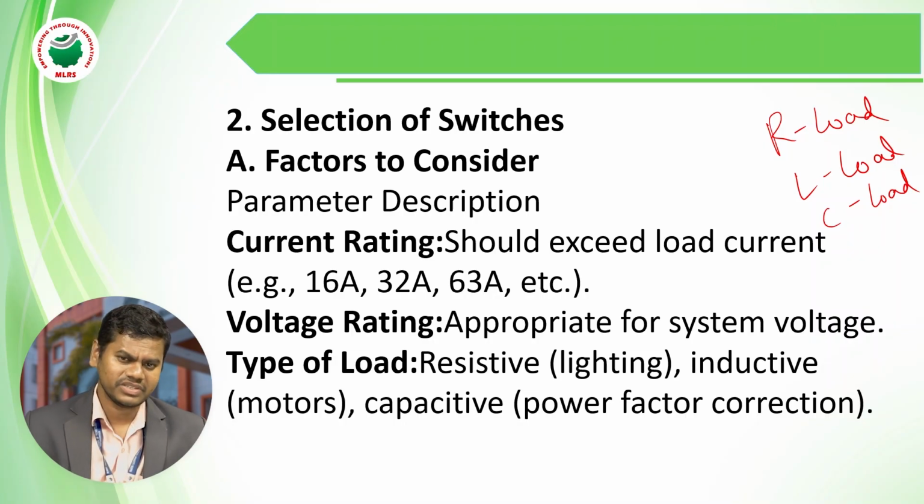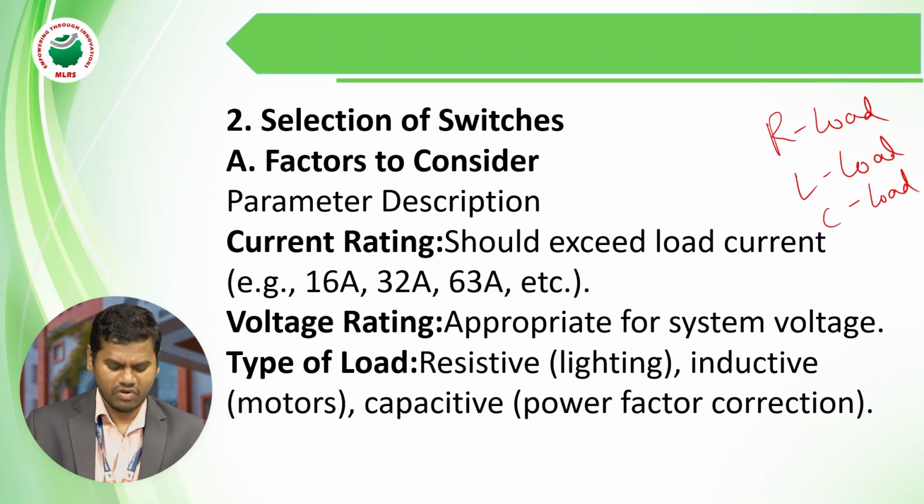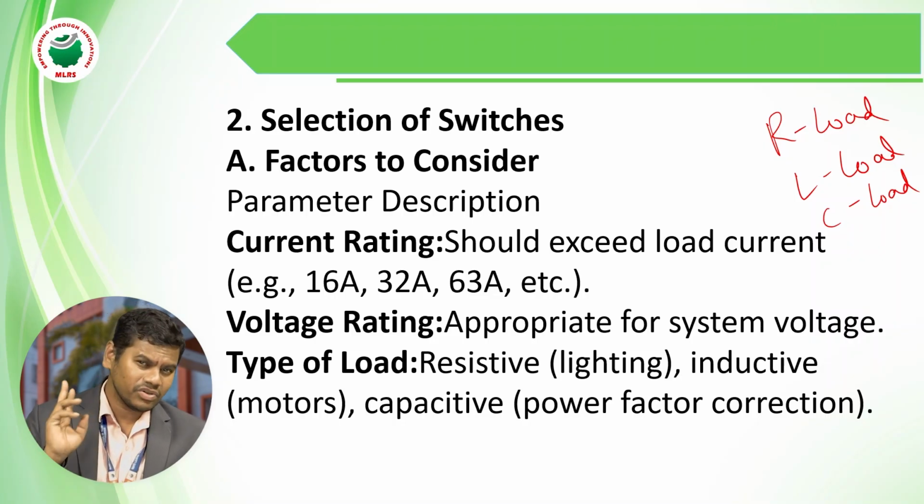So in the selection of switches, the factors to consider are the current rating, voltage rating, and type of load. The current rating should exceed the load current, that is 16 amps, 32 amps, 48, or 63 amps, etc. Next, voltage rating.